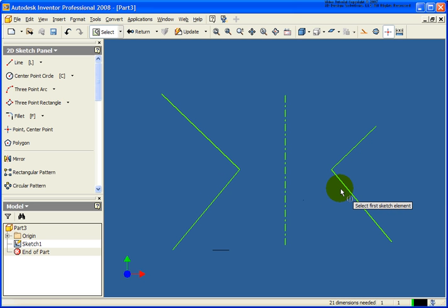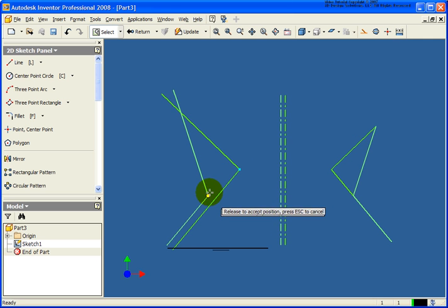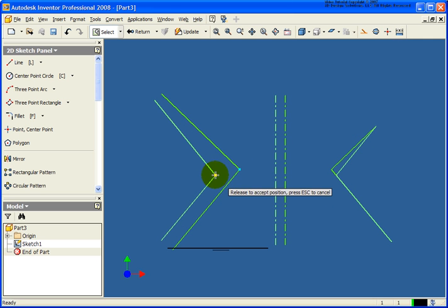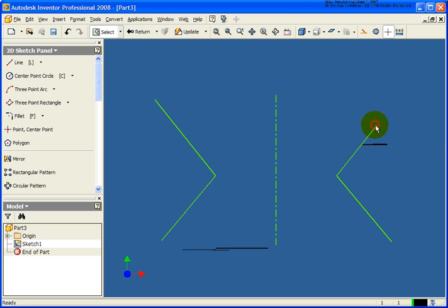Now, while I'm still in that tool, I no longer had to select the center line since it already realized that it was. So now if I stretch this out, you'll see that the angles are exactly the same. Of course, in this case, the size is not, so I can maybe apply an equal constraint to give the size on both lines exactly the same. So the symmetric constraint is allowing me to go back and define the angle for each of those line segments.